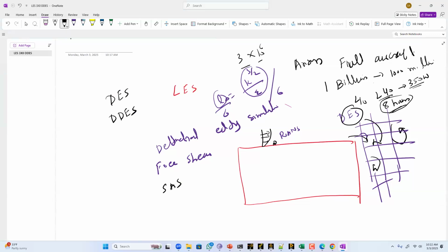So they have a delayed version; the first D here is for delayed. Then they have IDDES. This is to improve it further, with some shielding functions, and the shielding function can save you from switching to LES mode very early on.